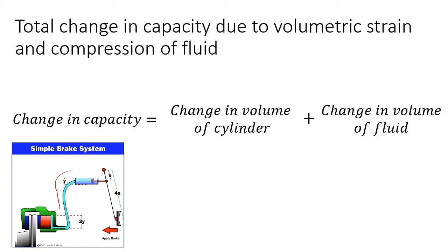And we have some limitations on this. Well, first of all, we've got an amount of energy, haven't we, that we need to dissipate. So this energy here from the vehicle that we want to slow down. And we've got some limitations here on the brake pedal, because we can only have so much movement of that pedal for us to be comfortable in pushing on that pedal with our normal range of movement. We can't have that amount of movement too large.